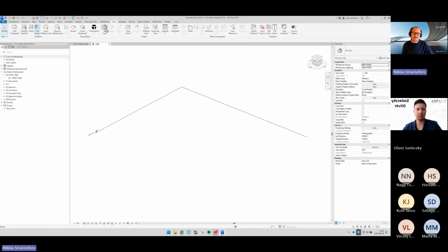And in our template, we have one level that is minus 10 meters. And that is just basically we need to have a level. I call it base level. I did that and I hope that no one calls their level base level. I have a unique name. I have to have it. So that hence why it's there and why it's kind of below water level, minus 10 meters.